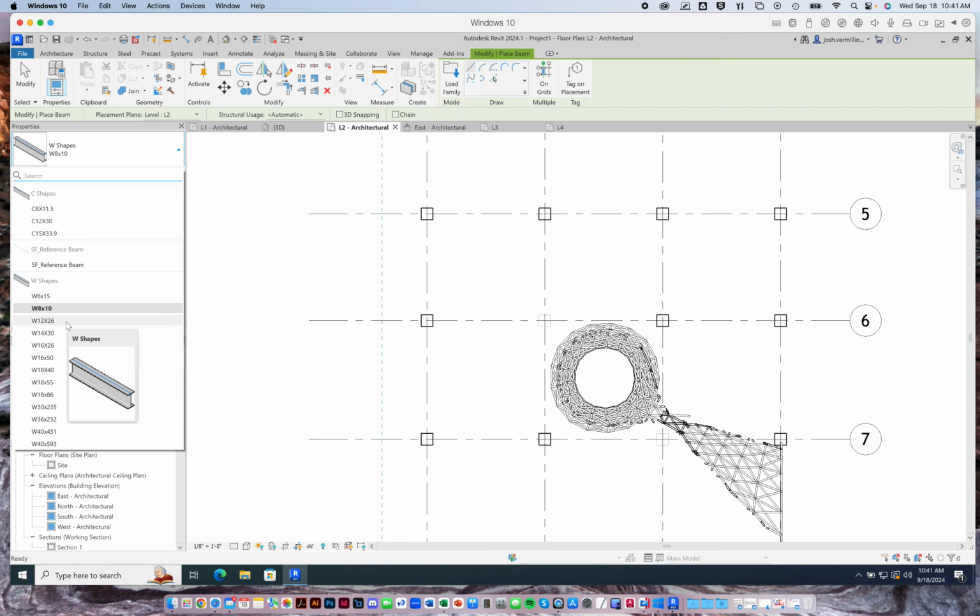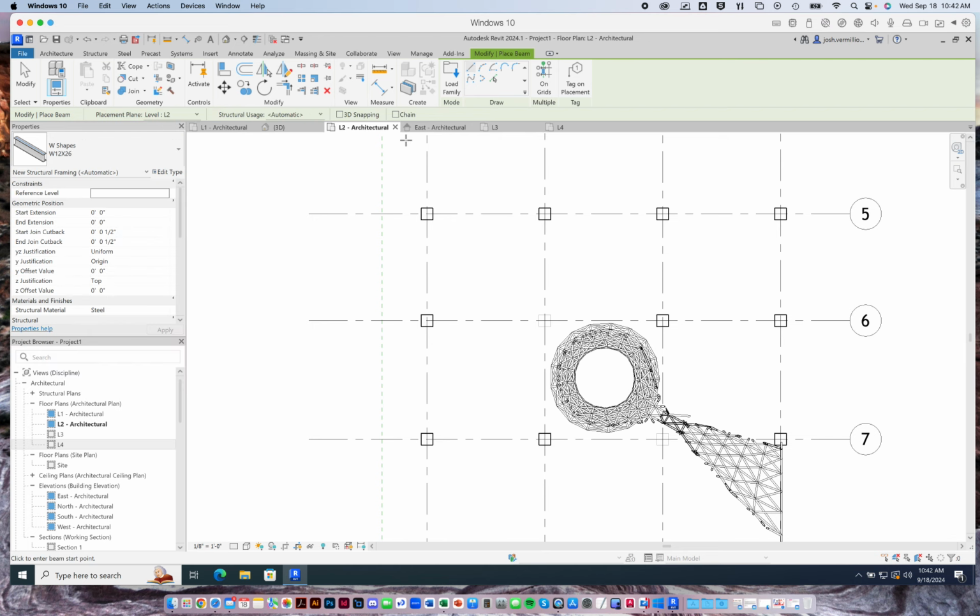And that talks about how beefy the flanges are, and it also might be the webbing. So the more dense it is, right? Imagine 50 feet for every linear foot. Like dead weight that, now put two of them together, 100 pounds, just 2 feet of beam, right? Steel's heavy, no? All right, so what we'll do is we'll go ahead and we'll stick with W12s by 26, right?